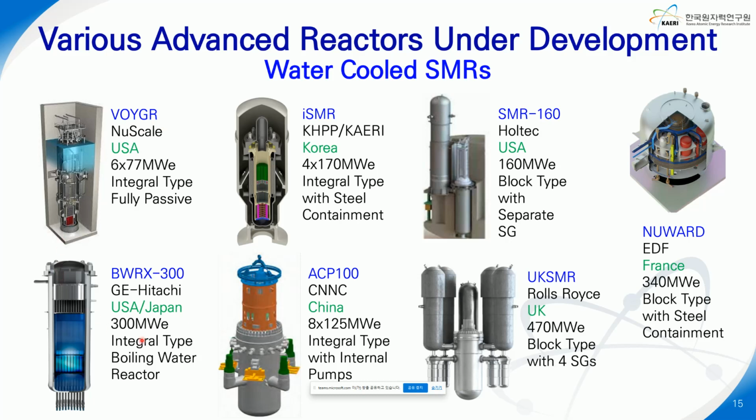These 4 are the integral reactors in which all the major components are placed in a reactor vessel. This integration makes the flow path complicated so that 1D flow simplification cannot be used. This flow modeling limitation becomes more severe in some reactors which employ passive core cooling.